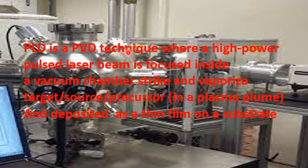So the precursor material in a physical vapor deposition technique is either evaporated or ablated, and then it is transported without any chemical reaction inside the chamber onto the substrate, and deposited as a thin film. Dear student, PLD is this kind of method. But the difference between pulse laser deposition and other physical vapor deposition techniques is that pulse laser deposition uses a high power pulse laser.